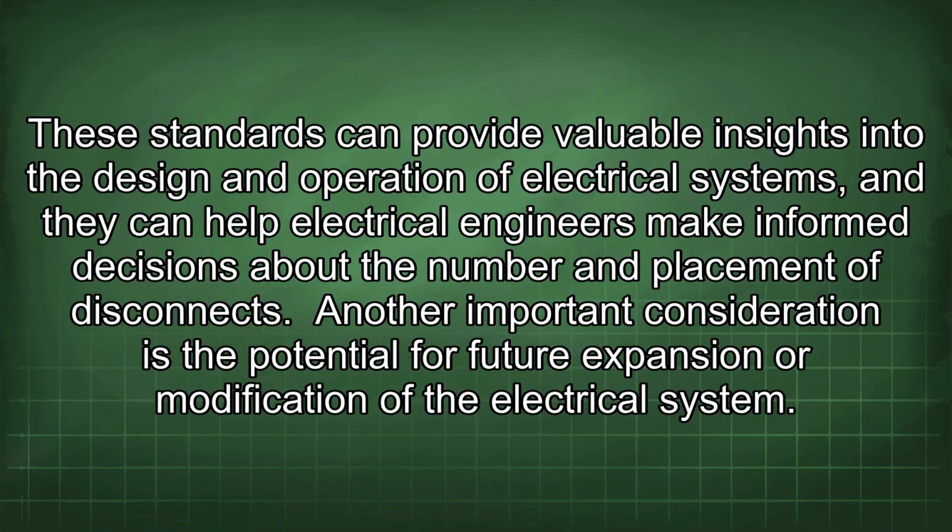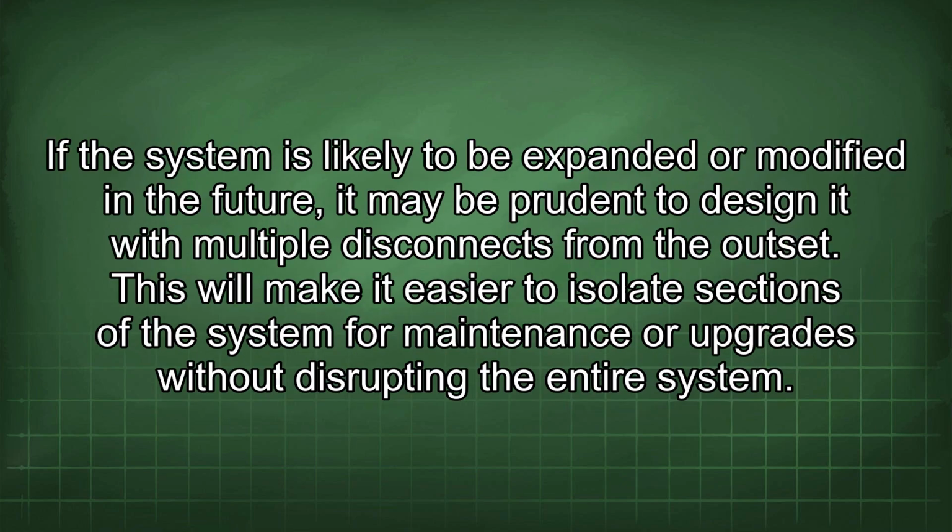Another important consideration is the potential for future expansion or modification of the electrical system. If the system is likely to be expanded or modified in the future, it may be prudent to design it with multiple disconnects from the outset. This will make it easier to isolate sections of the system for maintenance or upgrades without disrupting the entire system.